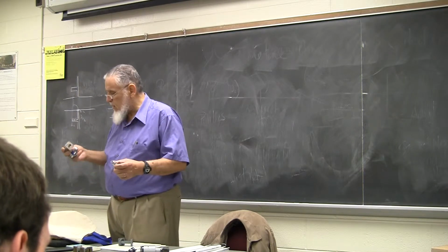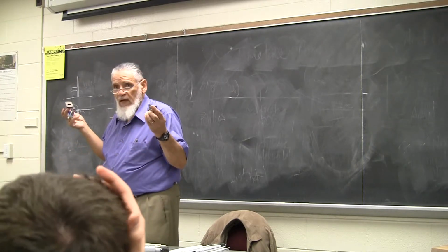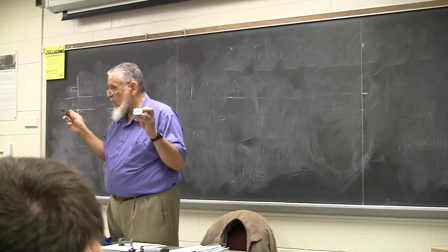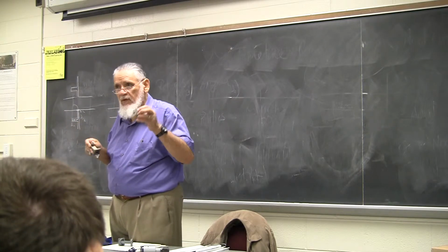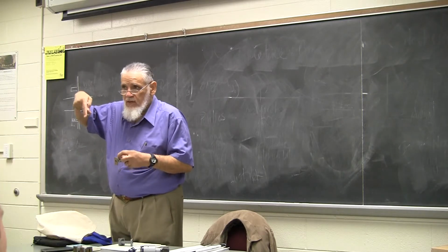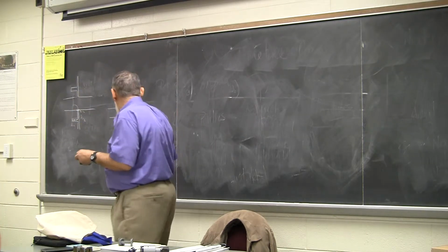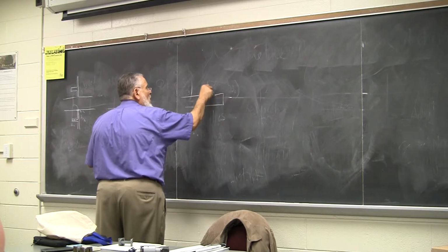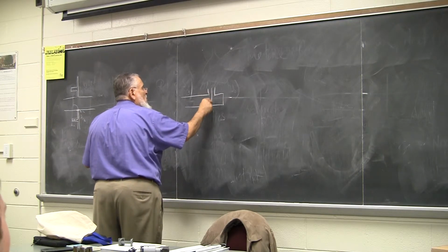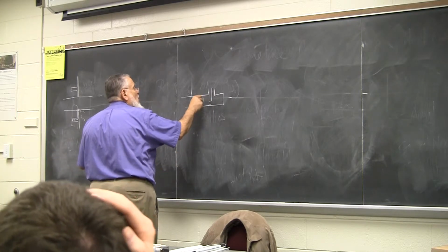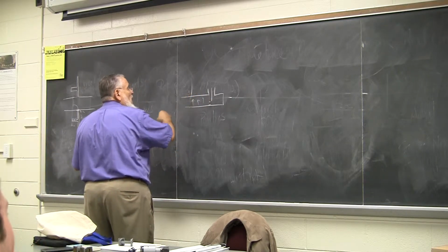Now these two are adapters, coax to waveguide adapters, right? And there are two types here. One of them is the electric field adapter, where you have an antenna probe that is sitting there inside the guide like this, that eventually causes the electric field to propagate.